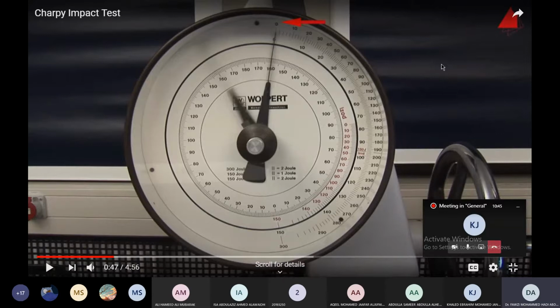So this is what is made sure at the beginning, that it goes to 0, as you could see there, with a free hammer, with a free movement or a free fall, no energy is absorbed. So it shows that it is 0 there. This means that we have a good machine there. The lubrication is good. That's to start with. The machine is ready for the tests.